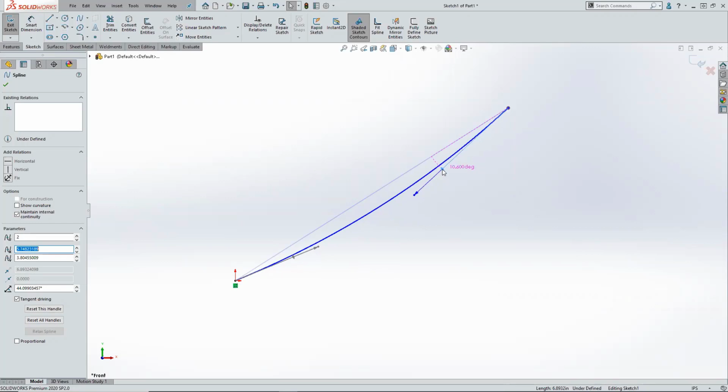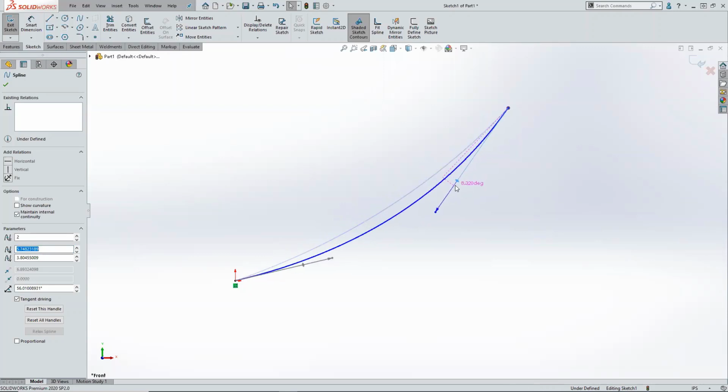If you can read that, it says about 10.6 degrees, and what that's telling me is that I've just moved it 10.6 degrees. If I leave it there for a second and then move it again, it's telling me I've moved it 7, but that's 7 from where I started, which is really kind of academic, but it's a point of reference. So the diamond gives you the ability to control the angle of the direction vector from this point. It's not of the line. Everything is being driven from the point from which this thing is emanating.